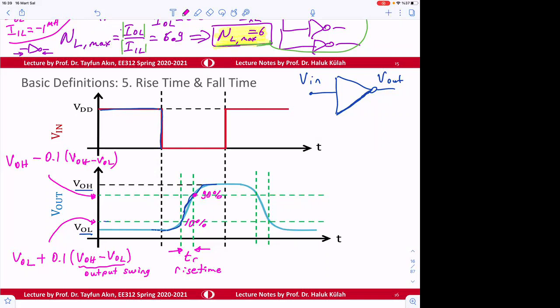I mean, at 10% to 90%, the signal at 90% still seems to be high, and at 10% seems to be low. So that's good enough. They have to make a definition, and that's how they make it. It's an engineering approximation: 10% high, 10% low is not that critical, so let's define it accordingly. Sağ olun hocam. Okay, sure.